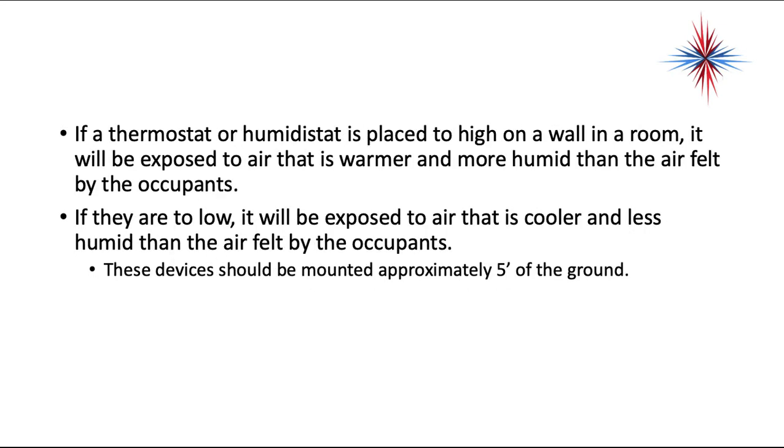If a thermostat or humidistat is placed too high on a wall in a room, it will be exposed to air that is warmer and more humid than the air felt by the occupants. If the thermostat or humidistat is too low, it will be exposed to air that is cooler and less humid than the air felt by occupants. Thermostats and humidistats should be mounted approximately 5 feet off the ground.